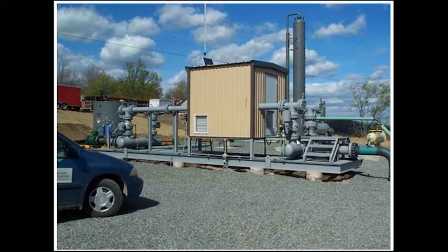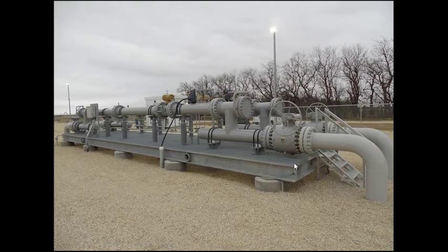Underneath there is a common center-fed header that links the two meter runs together. And I'll show you in a minute another disturbing opportunity. But this arrangement does not necessarily take into account all possible distortion opportunities if only this segment from here to here is flow calibrated in the lab.